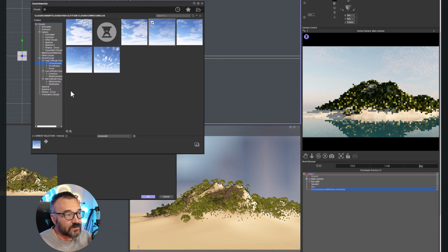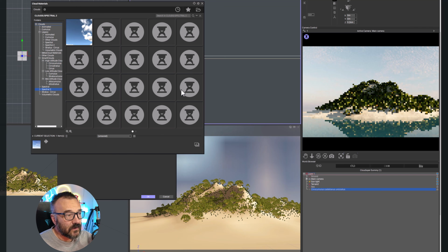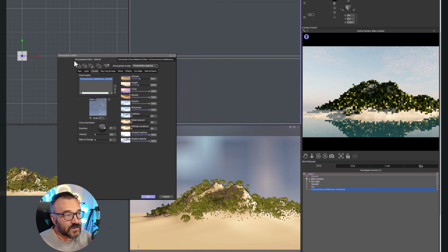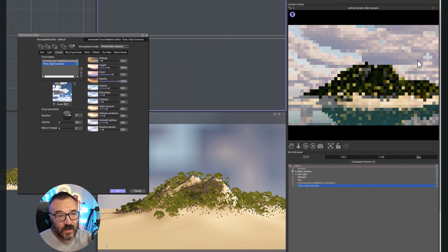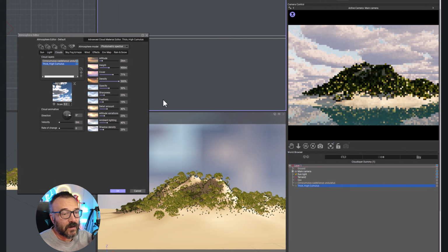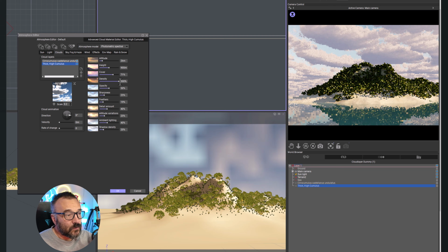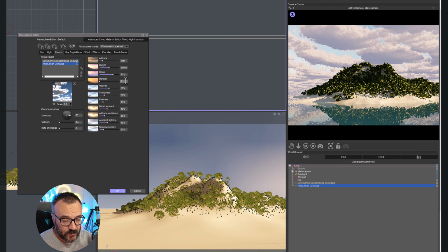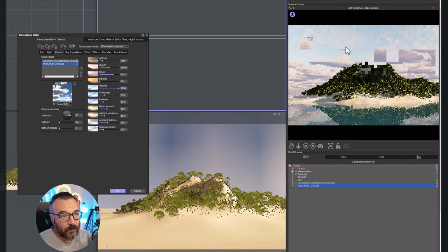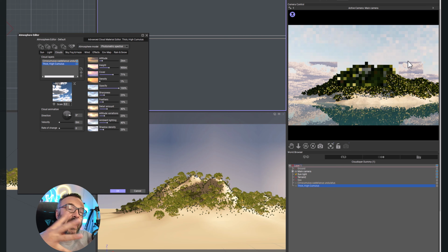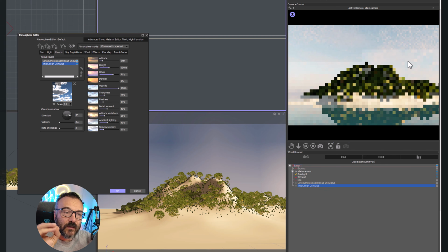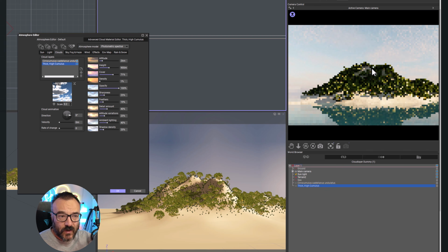Now in this case not smart, we're going to Specular 2. From here, let's just select simple fluffy clouds, and you can see they will upload there. But I want them to not be so heavy. For this, we'll take the density and put it at 0.1. Actually, you can go 1%. Oops, sorry. Let's go 1% on the density. We'll increase the opacity a little bit, and you can see it adds these floating, beautiful clouds around, and that's what we're going to do.